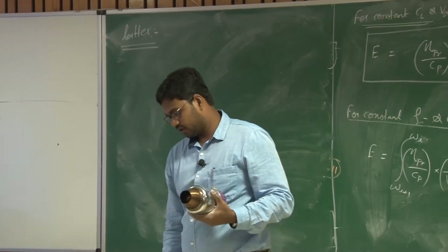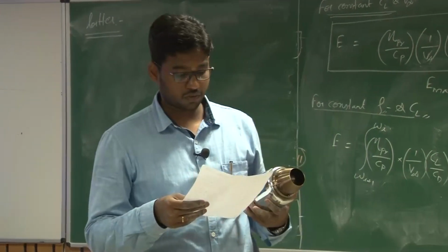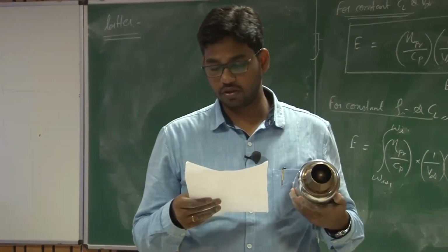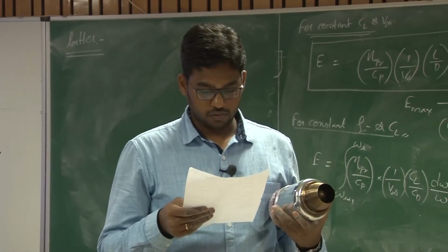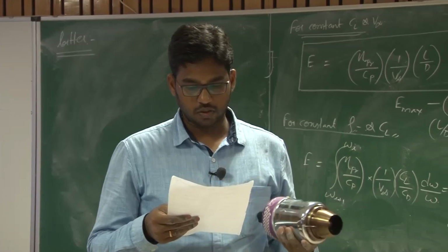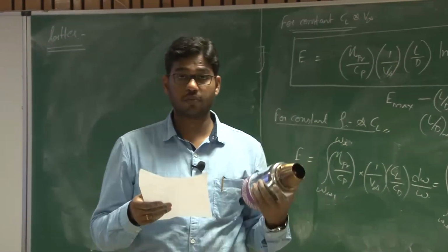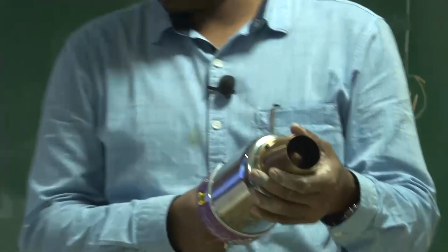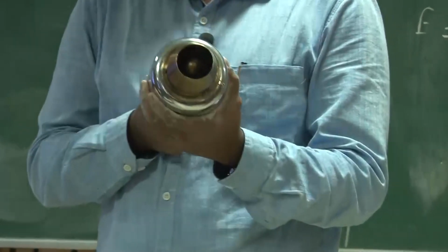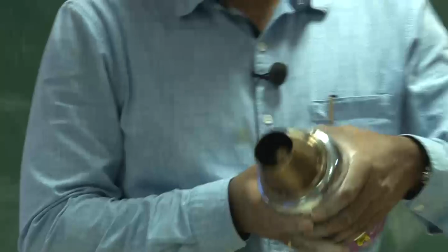Maximum thrust is about 220 newtons at 1,17,000 RPM. The RPM has a range of 35,000 to 1,17,000 RPM. It has an idle thrust of 9 newtons, which is approximately 1 kg of thrust, right? The length is 30 centimeters and the diameter is 11 centimeters, right?